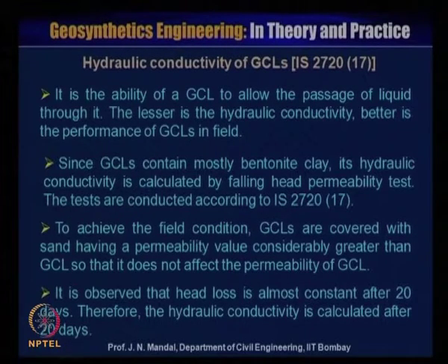These tests are conducted according to IS 2720. To achieve the field condition, GCL is covered with sand having a permeability value considerably greater than the GCL, so that it does not affect the permeability of the GCL.